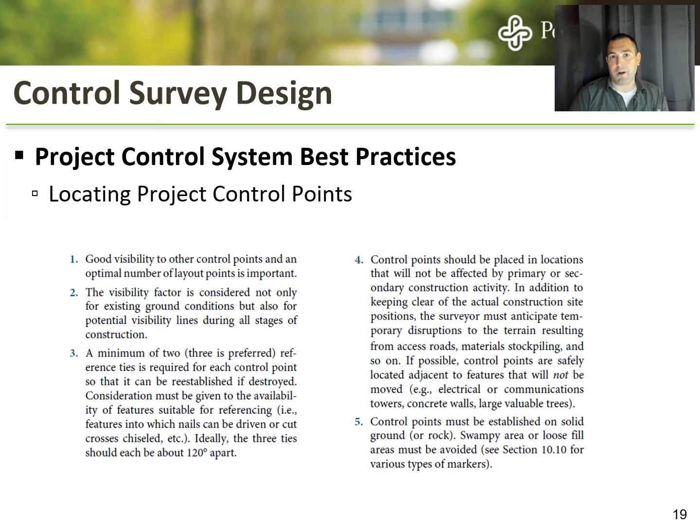Setting temporary monuments, you don't want to put them in things that are going to move. And sometimes things seem like they shouldn't move very much, like concrete slabs, but if they're doing a bunch of work here and there and undermining the slab, you've got to think about that as well. The other thing is you can't plan for everything perfectly. Things might change, and so having redundancies in your system is also a really good idea.